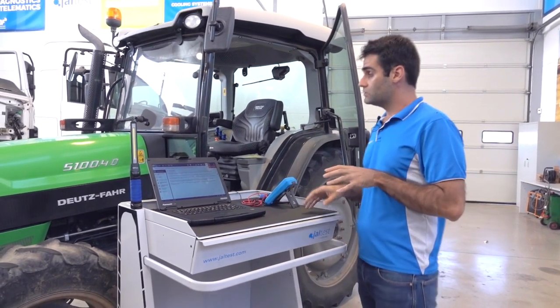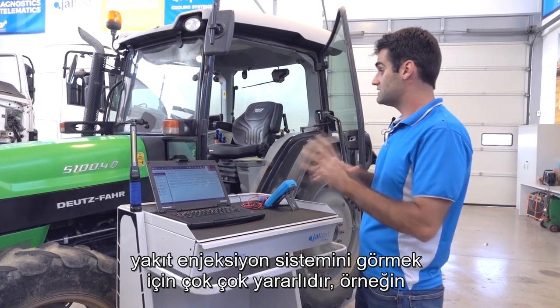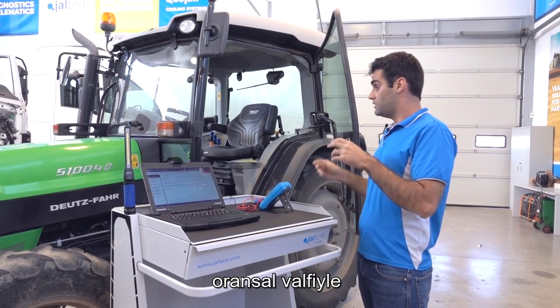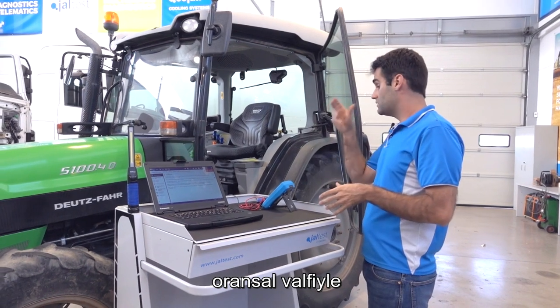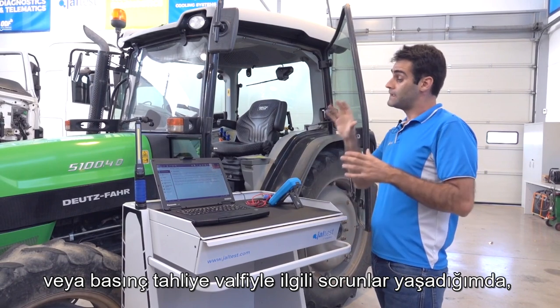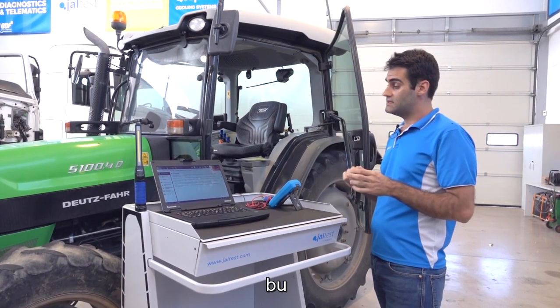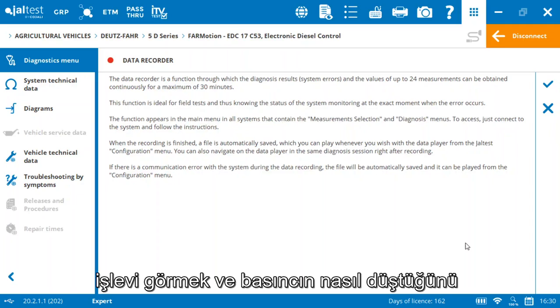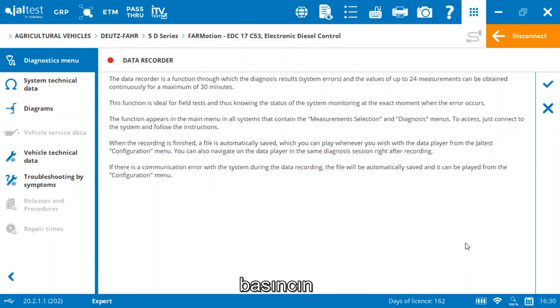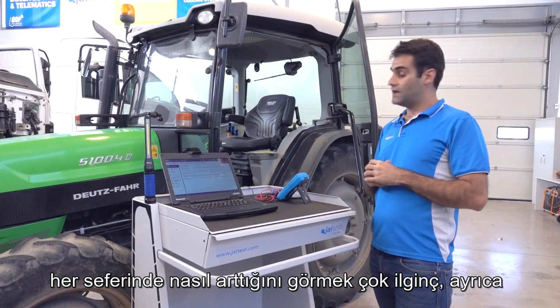That's very, very useful to see the fuel injection system, for instance. When I have problems with the fuel pump, the injector rail, the proportional valve of the fuel pump or the pressure relief valve, it's very interesting to see this function and see how the pressure drops, how the pressure relieves or how the pressure increases every time.